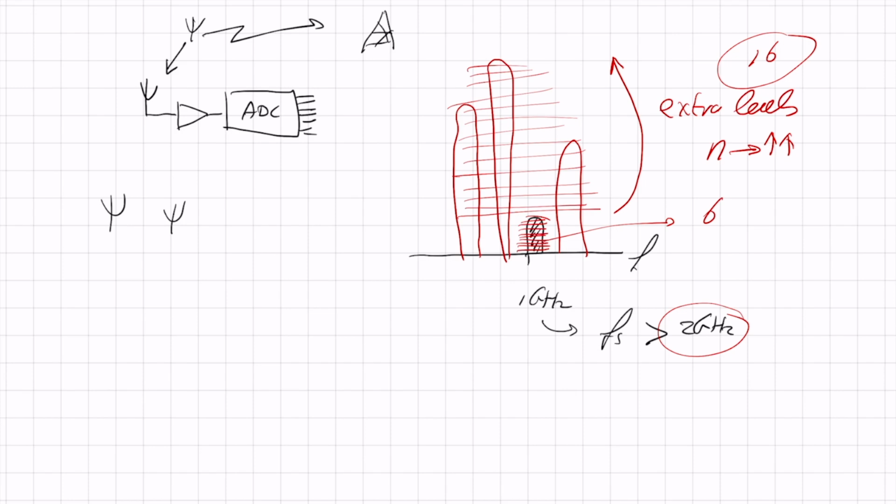And then if I take that figure of merit that I just introduced, I end up with a power in the order of 100 watts. Well, that's a bit painful in your pants if that's in your phone. So that's not a good idea. So this is why we need to do something analog before we go to the analog to digital converter.